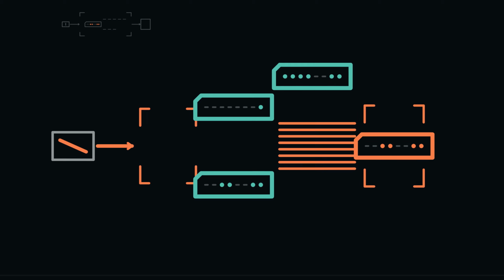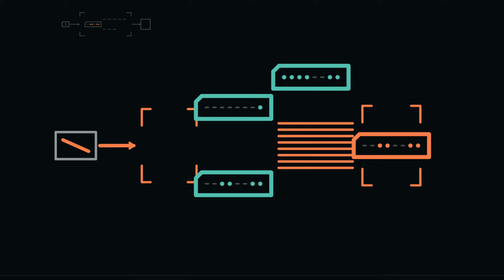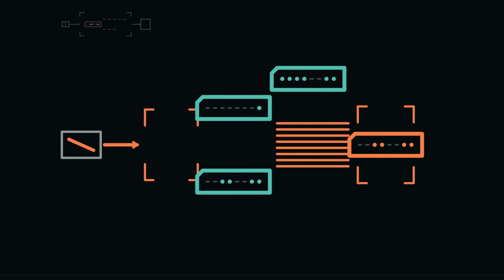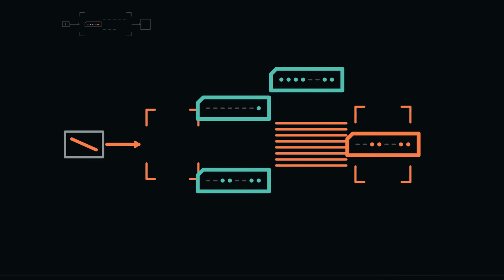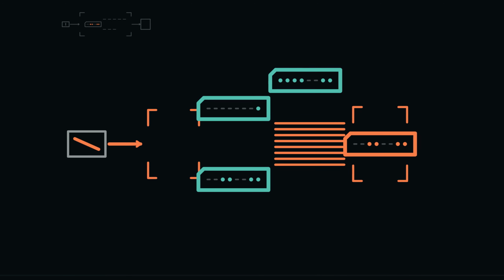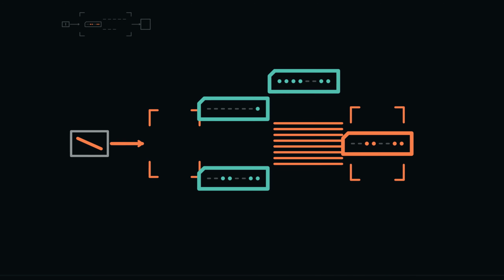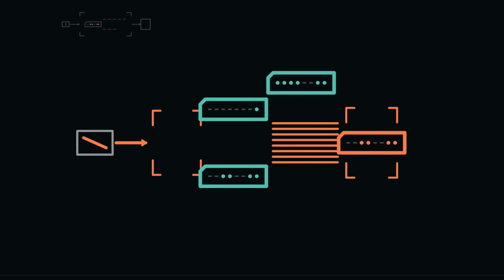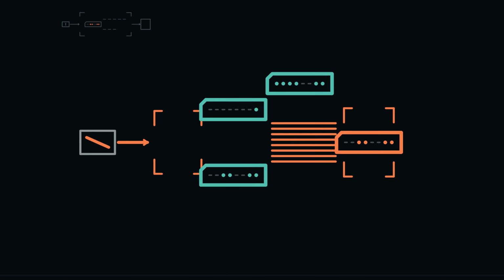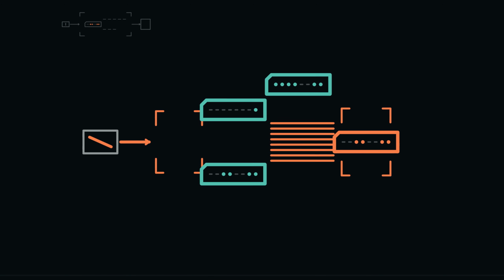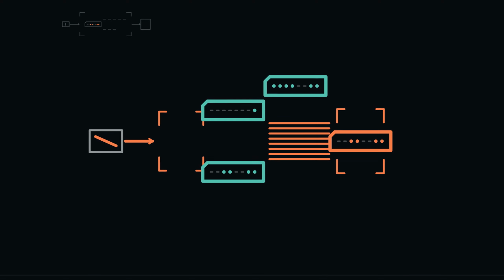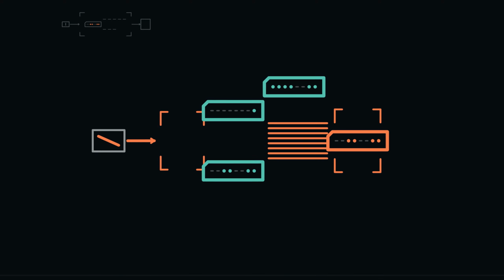Watch an input transaction at the processor boundary. A load instruction sends F0 as an address, receives status, and leaves the device queue unchanged. After the program observes ready, another load sends F1, receives the data byte, and changes the queue because the data register contract says read and consume. No special input instruction is hiding in the controller. The same load machinery is reused while the addressed receiver supplies the device behavior.